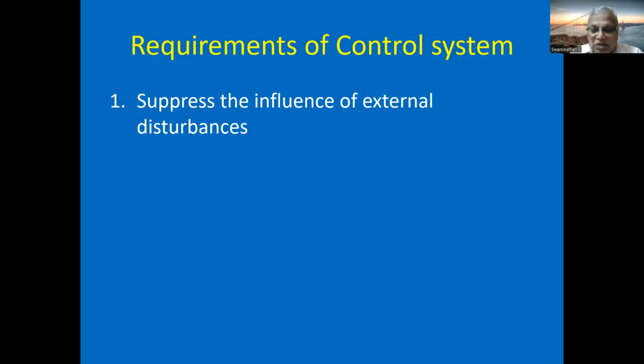Similarly, the steam pressure you specified as 5 atmosphere suddenly drops, steam temperature drops, or the quantity of steam used to heat the oil drops because of some problem elsewhere. So the process is disturbed by external factors. The steam flow rate is reduced or the inlet temperature is reduced: external disturbances.